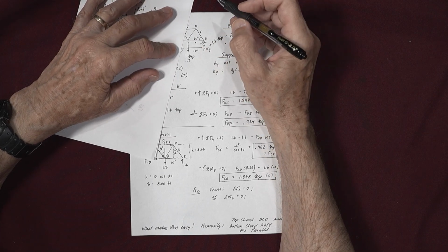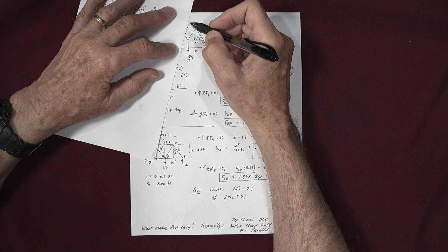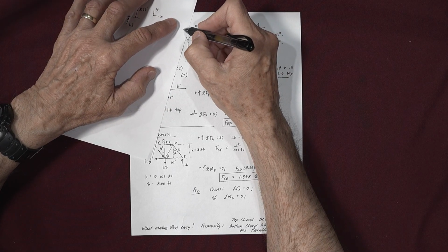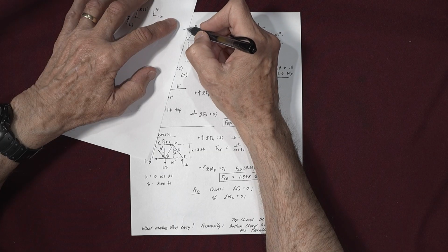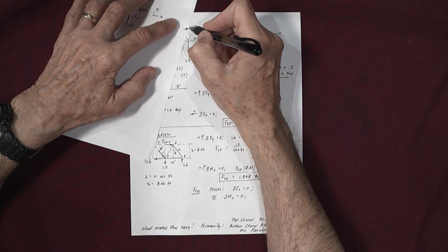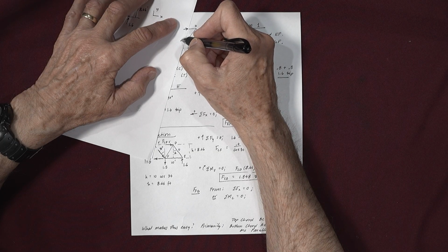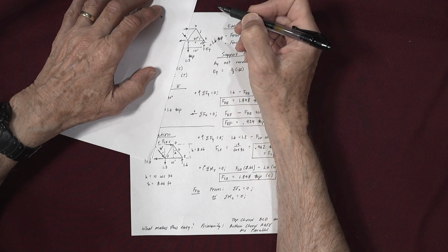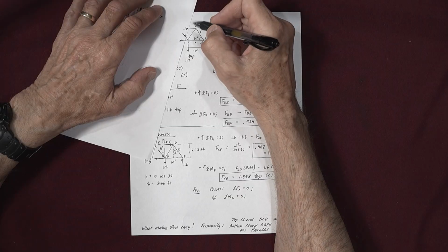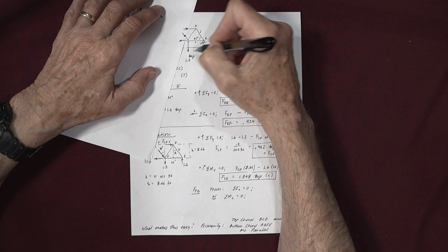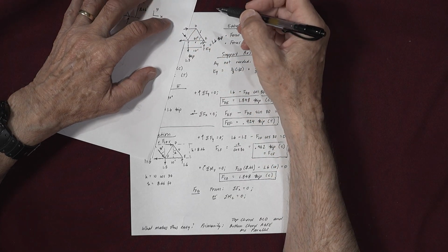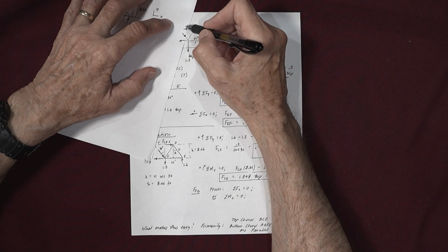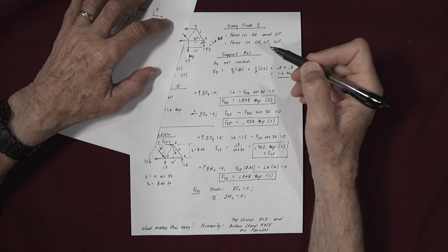And especially on a complex truss, if you lay your index card here, this is your right-hand free body. And then this guy is in compression. This guy is in tension. And this guy is coming down this way. And so you can actually get a free body without redrawing the whole thing like I did. And on a test, that could actually save you some time. And you can get these directions on it.